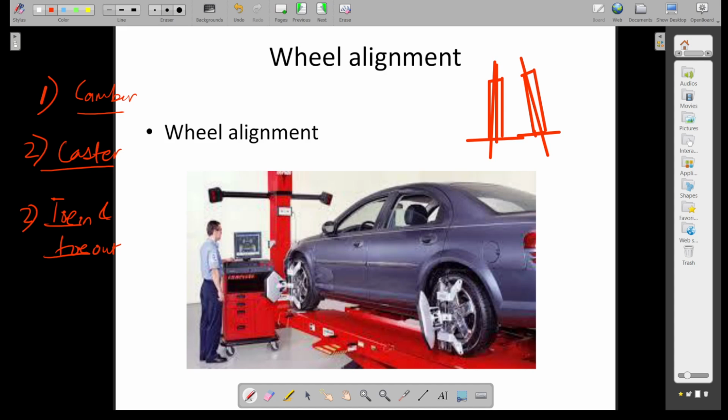When I adjust the camber, it is adjusted by an eccentric cam, which is located in the control arm shaft. When I go for the caster arrangement, I am inserting eccentric bushes or wedges in the suspension system.